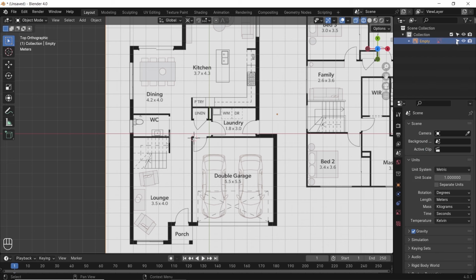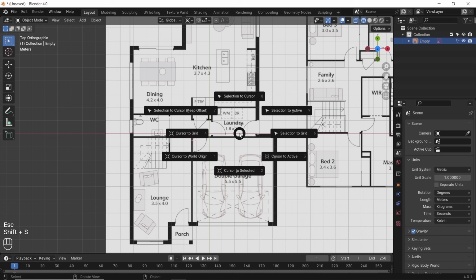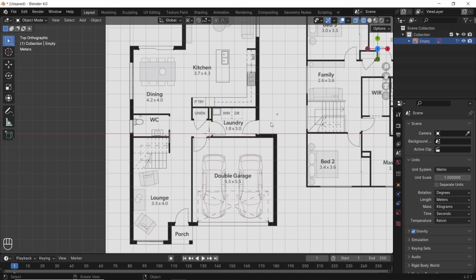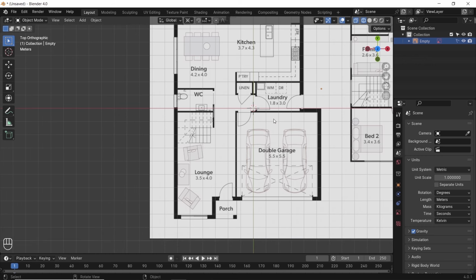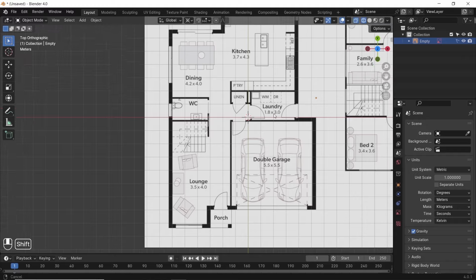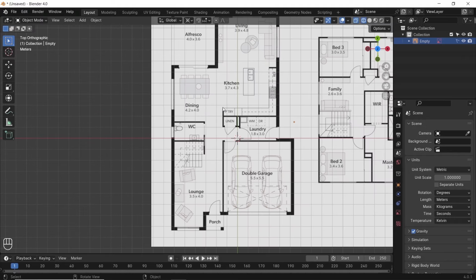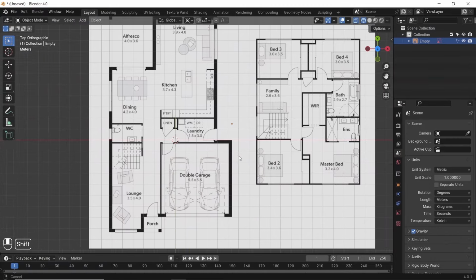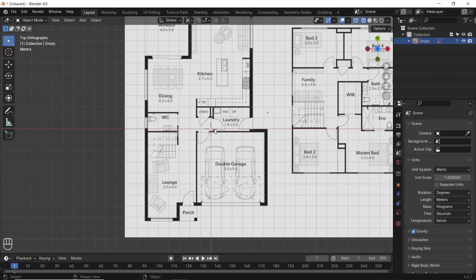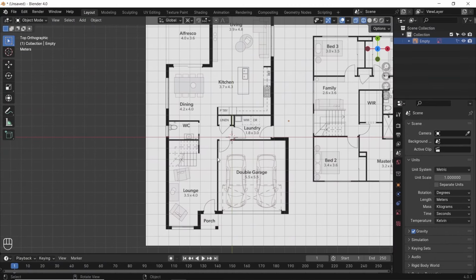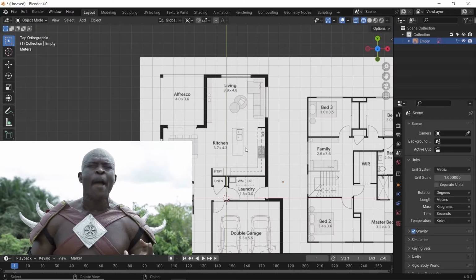You can start drawing from any area on this image, top or bottom. It all ends up together, and there are two main ways to do that. Either draw with surface or with lines. Surface is the method I go by, and it's simply adding a plane and tracing it along the image walls. The line method is just a vertex traced along the same walls. Then at the end, you add thickness to it, but that can generate problems at the end. So stick with the surface one, unless you're that guy. I want problems, always!